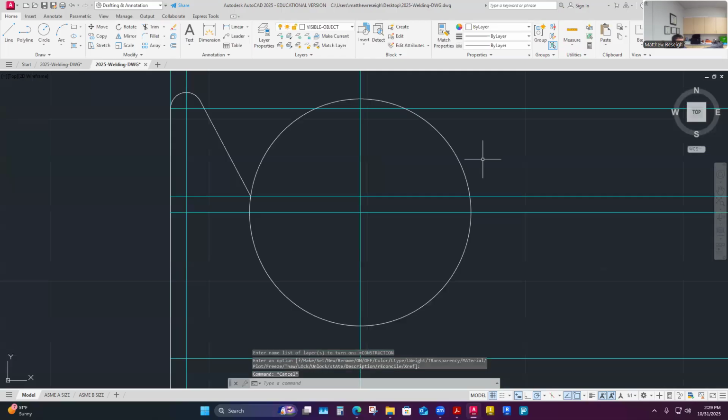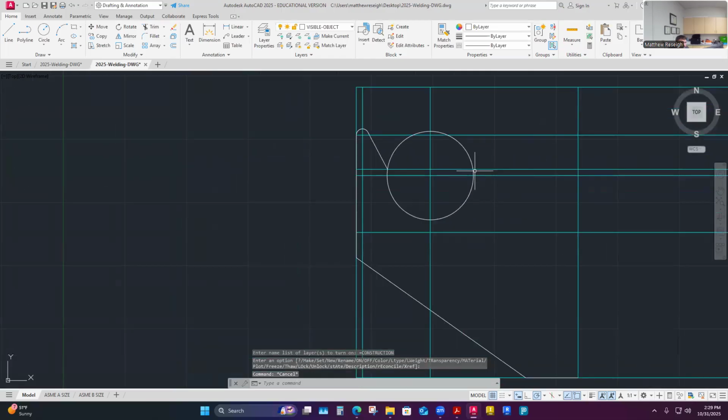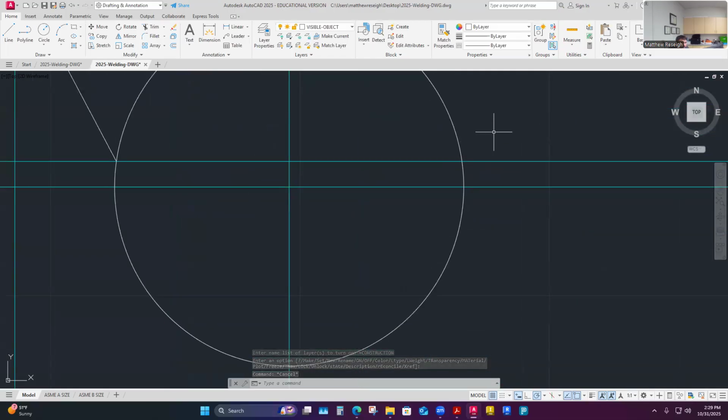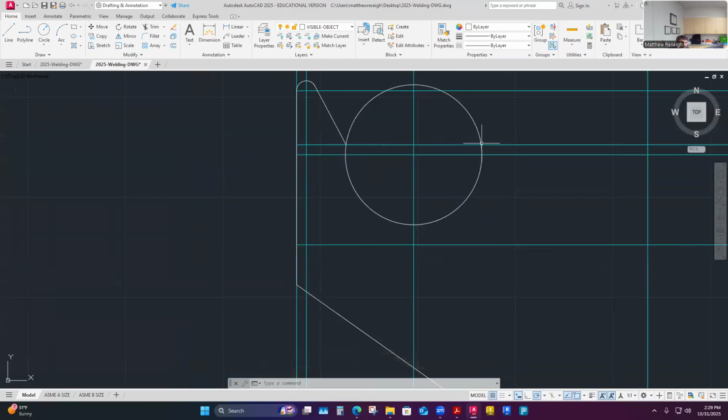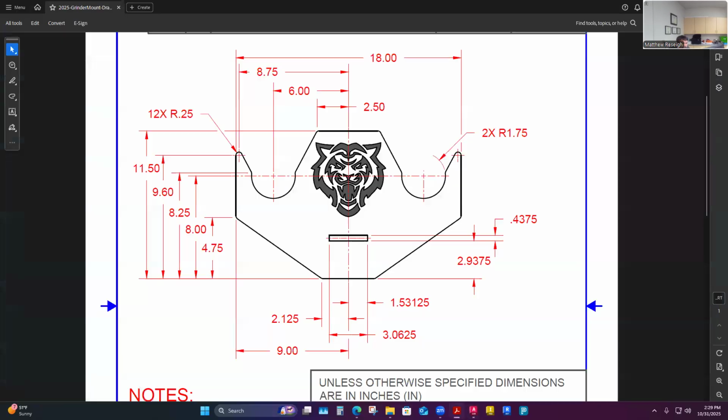All right, I've got that trimmed. What we need to do is establish maybe from up. We know this is the point where it turns up as well. That was uniform across, and goes up to some other line. I think we have that over here now, so we're just about done with this actually. Here's my 2.5 inch long line from center over, and then from that point, we connect those two points.